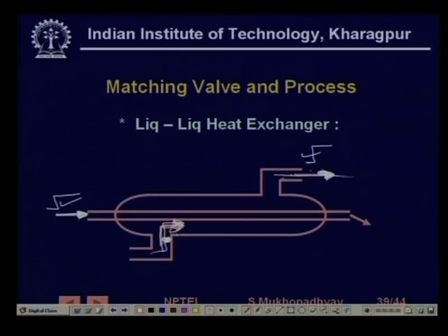So, as we know, the controller gain needs to be kept low in this region. On the other hand, if the flow rate is increased, the gain will fall and the delay will also fall. Now you can have a higher controller gain for improved transient performance, but it is not easy to change controllers automatically.